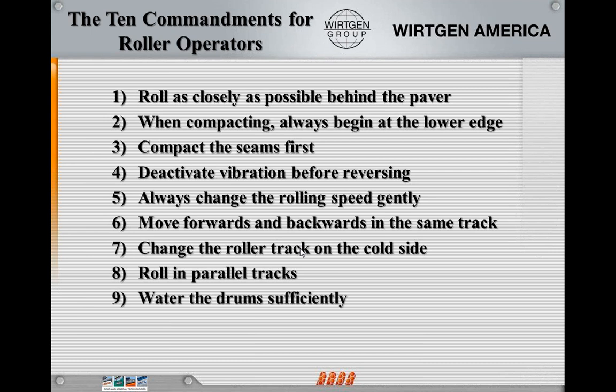Water the drums sufficiently. We only need enough water on the drums to keep from picking anything up. We don't need to be overdosing the water on the drums because it does a couple things. It uses too much water. We're going to be stopping and refilling too much. Plus, it cools the mat temperature down, so it reduces the ability to get the compaction.